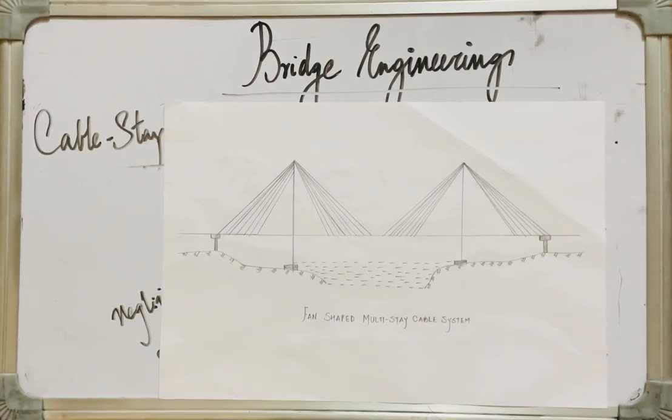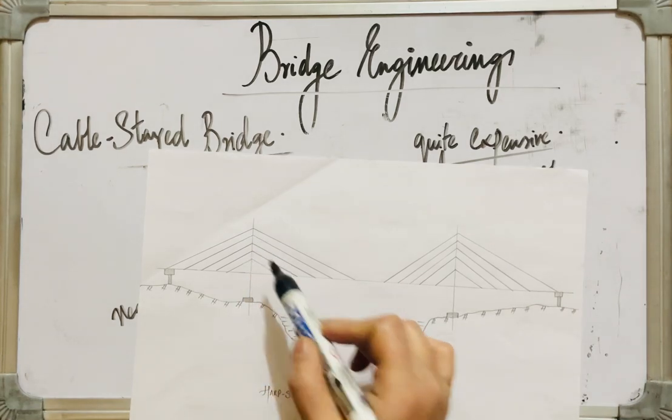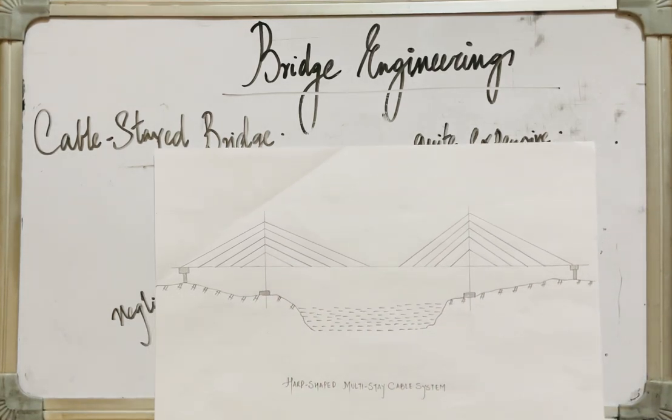The very important advantage of going for this cable and tower system is that we can eliminate the need for the intermediate piers, hence providing a larger width for the purposes of navigation, etc. And we can create longer spans by this assembly. And we have also learned that if the cables meet in a bunch at the tower, then that multi-stay cable system is known as fan shaped, or if they meet at multiple levels on the towers, then that is known as the harp shaped multi-cable stay system.